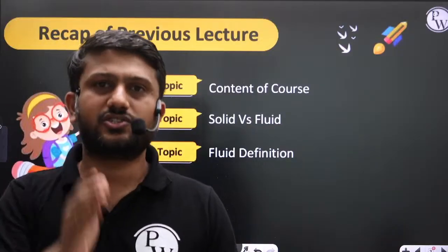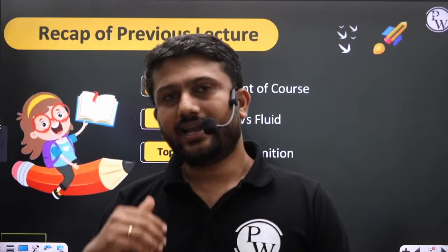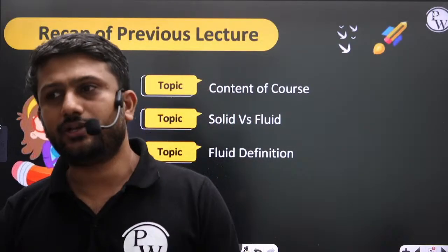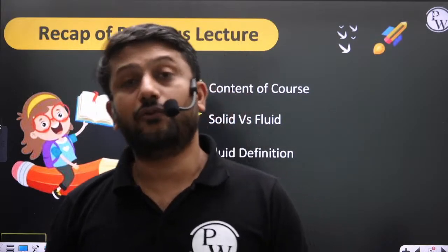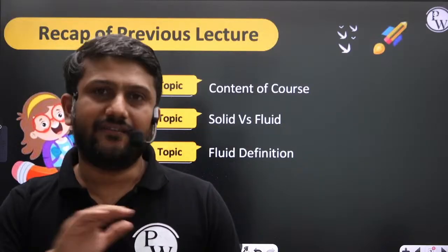A solid can resist tensile load, a solid can resist compressive load, and a solid can resist shear load by showing some definite amount of deformation. But a fluid never resists tensile load. A fluid resists only three-dimensional compressive load; one-dimensional or two-dimensional compressive load, a fluid never resists.